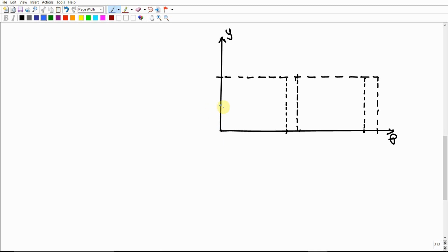Then you're going to use the compass to draw a circle. Fix the middle tip here, then touch with the lead tip at either this point or this point. Then you're just going to draw a circle. Make sure that the circle is a perfect circle, not like this, because I'm just using my hand since I'm using other tools for this video. But you have to make sure that this circle is a perfect circle as much as you can. Definitely you have to use the compass to be accurate.